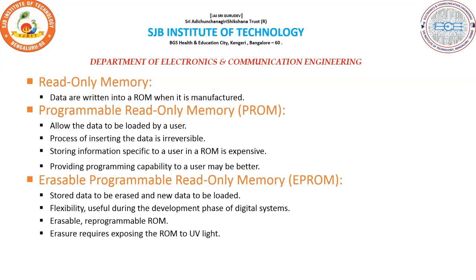The ROM is economically attractive for storing fixed programs and data when high volumes of ROMs are produced. The cost of preparing the mask needed for storing a particular information pattern in the ROM makes them very expensive, because it is programmed while manufacturing. So it is quite expensive when only a small number are required. When a large number of ROMs is not required, we go for PROM, which provides a faster and considerably less expensive approach because it can be programmed directly by the user.